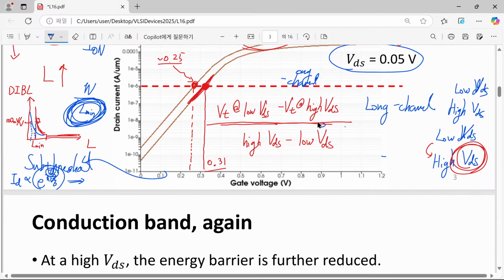when a technology is quite weak against DIBL, it means that this technology is approaching its extreme for normal operation. If there occurs any kind of variation in the real fabricated transistor, then your transistor will show quite a big difference in the threshold voltage.